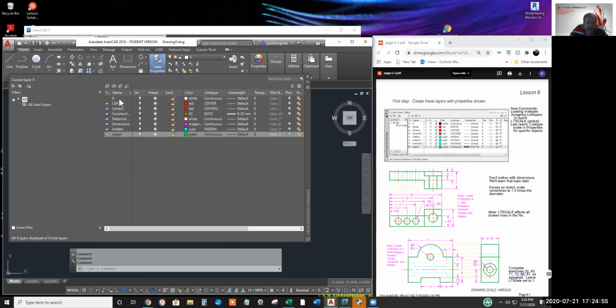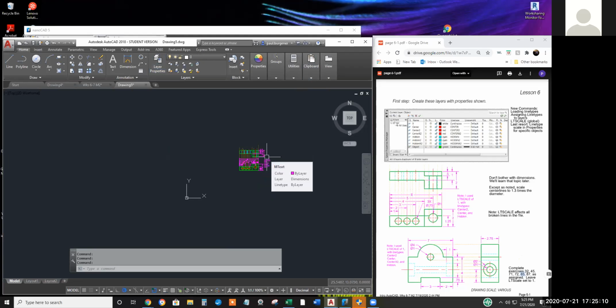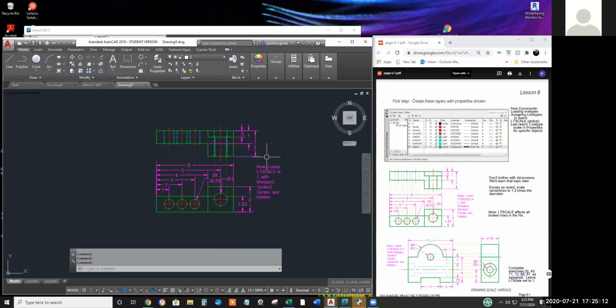And we got a couple of center lines. I think what happened was you already had an object layer in the current session, so it just merged the two. That could be. You had zero and object. There were two of them in there. Interesting. Mystery solved. Yeah, the drawing that receives the stuff governs when there's a difference in layer properties. That's logical. You're right. Yep.